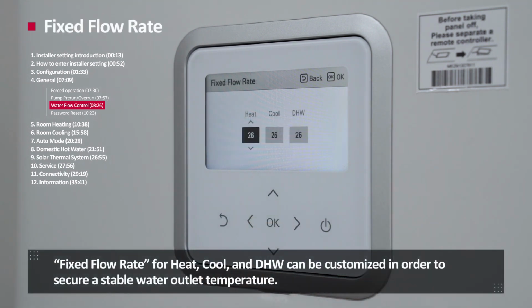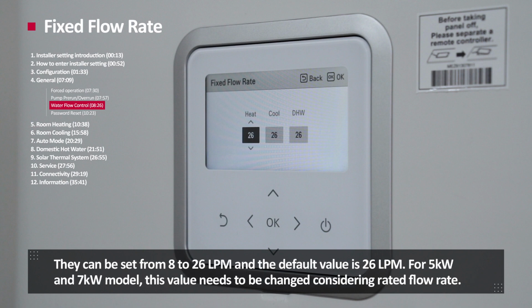Fixed flow rate for heat, cool, and DHW can be customized in order to secure a stable water outlet temperature. They can be set from 8 to 26 LPM, and the default value is 26 LPM. For 5 kW and 7 kW model, this value needs to be changed considering rated flow rate.